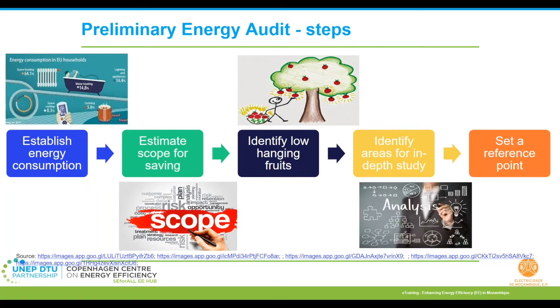The next step is about identifying the areas that might require more detailed study and measurements. Of course, it's not possible to address everything with just one look and a short duration of time. Some of them will need more time, and the auditor might have to get into the depths of the facility's operations. But based on experience and interaction during the preliminary audit, the energy auditor should be able to identify the potential areas which may require an in-depth study.